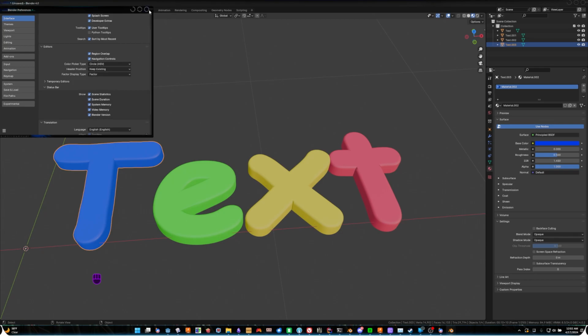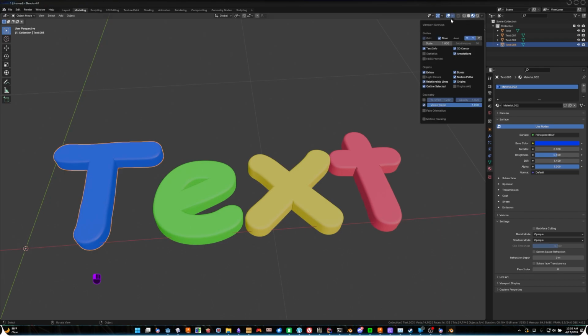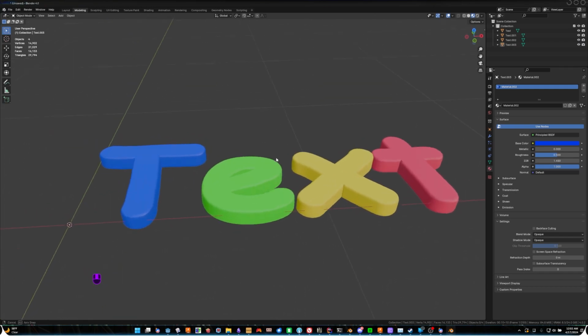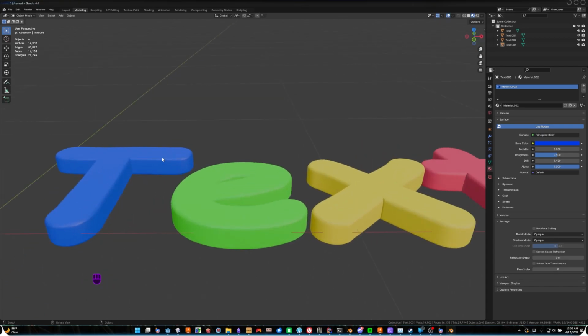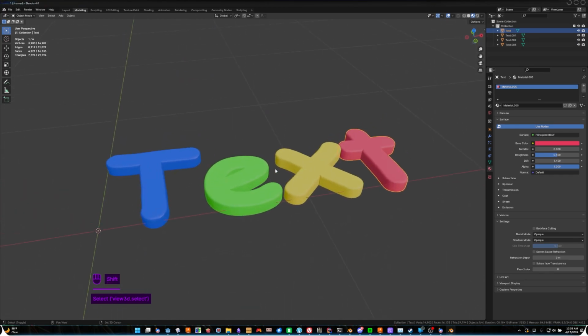But you can also put your scene statistics right here in the viewport. If you come over here to your overlays, you have statistics right here as well. And faces and poly are pretty much the same thing. Currently I have 4,689 faces of the 16,000 selected. That's the T that I have selected here. If I select nothing, then it just shows you the overview of all of the different properties. So that's pretty cool. And if I decided to decimate, I could reduce that down some, but I'm not going to do that right now. That's the modifiers. That's in the next lesson.